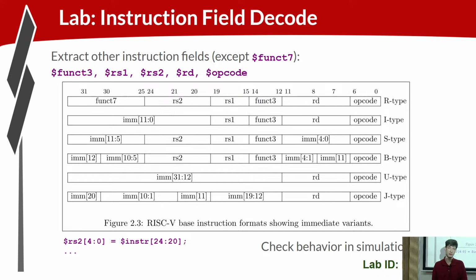The bits that are left over are used for immediate bits. So the R type, which uses both RS1, RS2, and RD, has no immediate. It uses the remaining bits for this funct7, which helps narrow down, well, actually it's not even really used, but it's available to specify more of a breakdown of the actual instruction that's to be executed. The other instructions maybe don't use both source 1 and source 2 or don't use the destination, so there are more bits available for immediate.